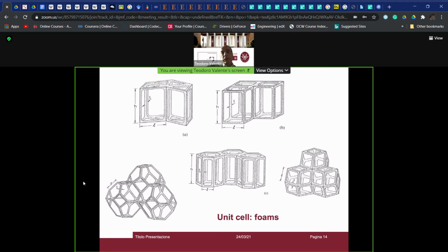And being a reticular structure, one of the general rules of reticular structures is that the beams are subjected inside only to compression or tensile stress. But we know that when we are discussing ceramic materials, they show a very wide scattering in terms of strength due to the unreproducibility of defects linked to the fabrication processes.